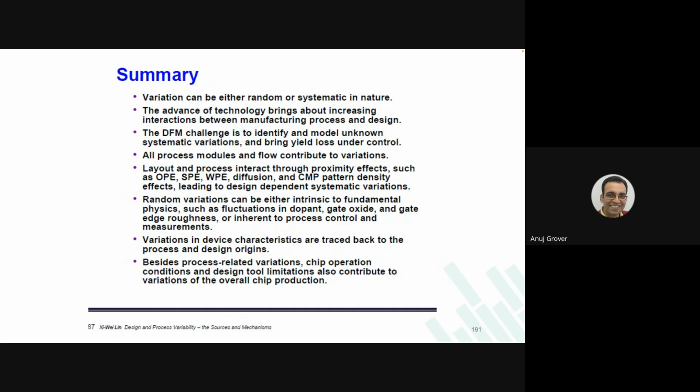So currents were also reducing and variations were increasing. There was a time when we said nominal current minus 3 sigma, let us design with that. But now in advanced technologies, because the capacity has increased, we want to qualify a higher sigma extent. Nominal current minus 4.5 sigma was negative. Now, how do you design with a negative current?